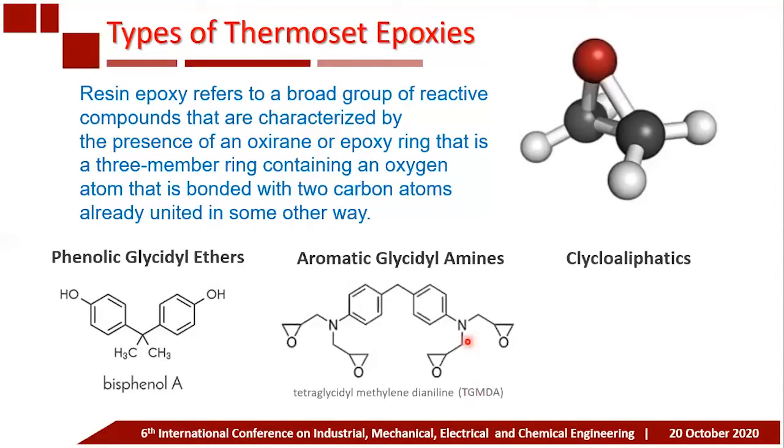The modification of this epoxy exhibits low viscosity at room temperature and is commonly blended with other epoxies to modify the flow or tack of the formulation without the loss of glass transition temperature. Other commercial glycidyl amines include tetraglycidyl methylene dianiline. The primary disadvantage of this class is cost; it is very expensive in the market.